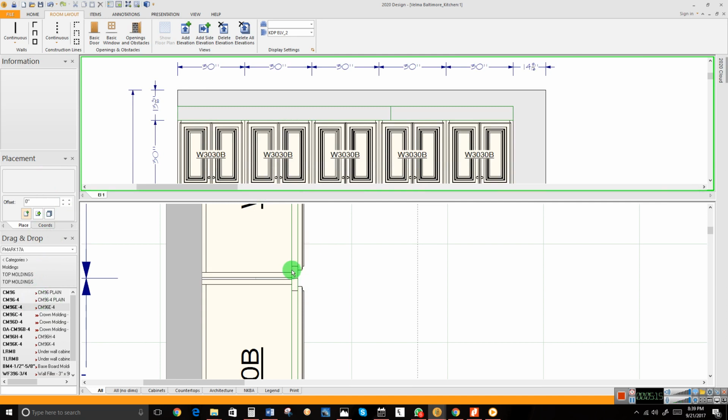What if you have like 5 different types of lines stacked over each other, and you're going to have to start thinking which one is which? So your best option is to look for it in the elevation. So you drag this and you place it right there. Remember, if you place it at the bottom, it's not going to go. If you place it above, it's not going to stack. So you have to place it on the face of the current molding